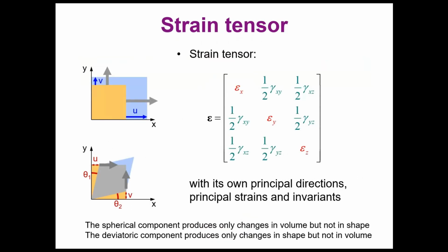So this is the strain tensor. It is related to the stress tensor, and as you know, the diagonal is just the axial strains, which control the volume of the cube we are considering. I have sketched it here in 2 dimensions for clarity, but of course this is the same cube in 3-dimensional space as in the definition of the stress tensor. And the distortions in green control or represent the change in shape of this cube that we are using to define the stress tensor and the strain tensor.